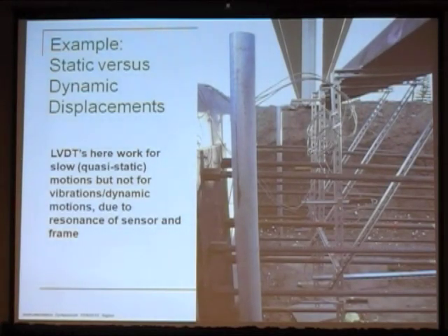And this is one example. These are LVDTs here. This is a load frame. This was a foundation test where we were doing quasi-static testing on a foundation. And it worked fine. We've got a reference frame at the top. We've got these beams hanging down. That's fine for static measurements, but if you tried to shake that at all, it became a problem for the low-level measurements, just the ambient vibration of this thing. It's not suitable for dynamic. And it's not just the sensors, it's the whole setup.